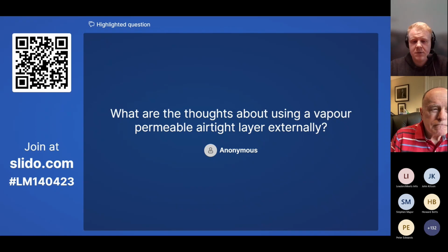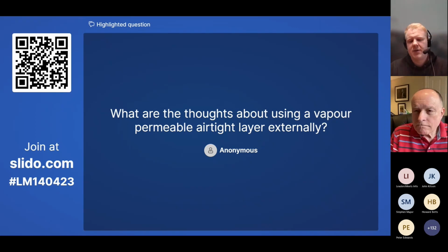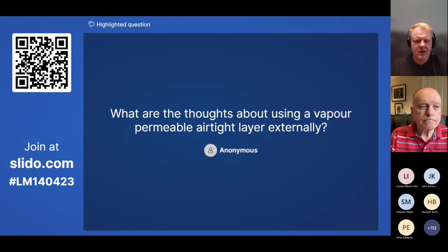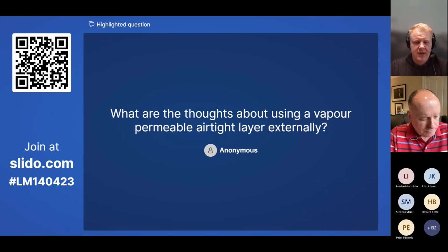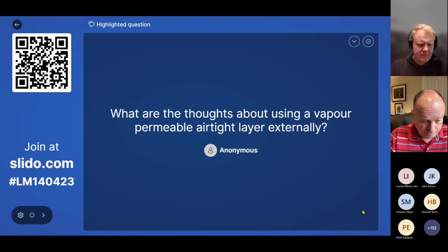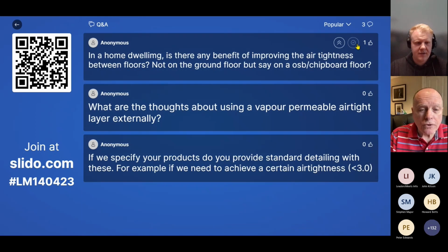But there are certain buildup cases where you have something vapor permeable on the outside, but in every case you have to take a specific look at it, because it's hard to say in general. The general way is something blocking vapor on the inside and something more open on the outside, but that's only for our region, and not generally overall. Okay, thank you.